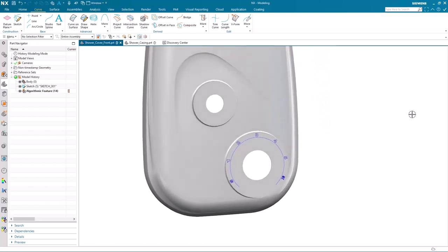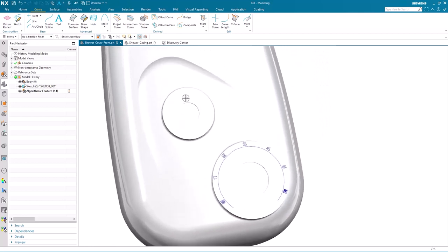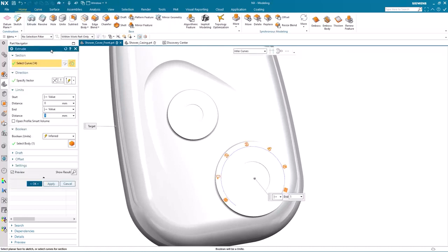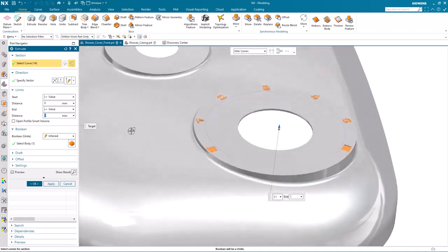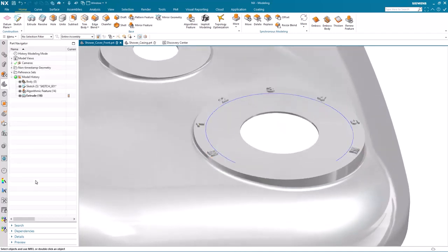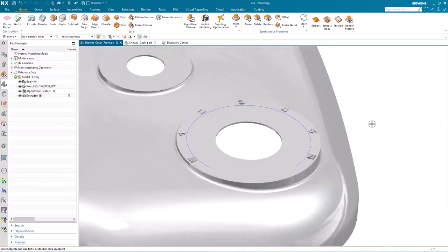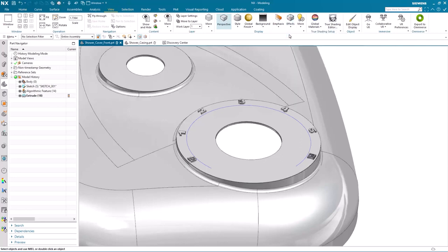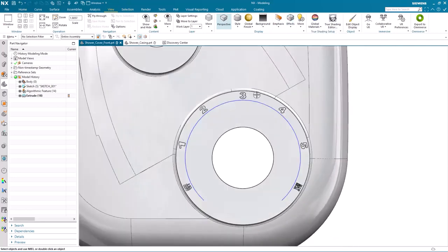So I've got my dynamic display. What I'm going to do now is to extrude the figures as solids and add them to the shower cover. Now this could have been part of the rule, and I may go back in later on and modify the rule to include the extrude. So let's go ahead and edit the rule and update the model.